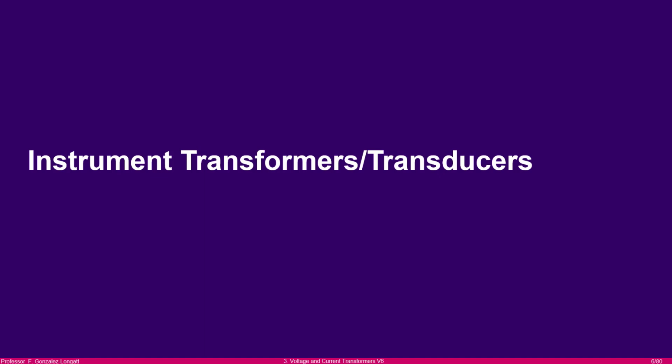As a consequence, we are moving to fully digital substations, and that involves all the processes, monitoring, sensing, and of course protections. That is the moment that we start to use the famous IEC 61850. All my students must be aware that IEC 61850 is making a lot of change in terms of how substations are built and how we need to project the future power system.